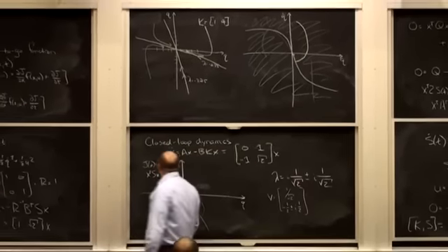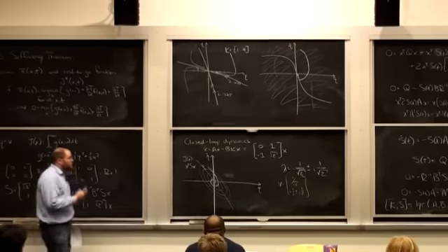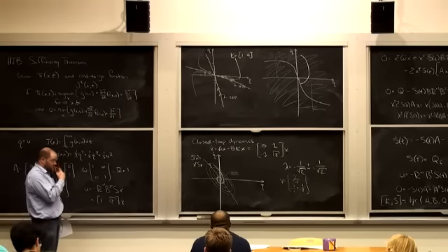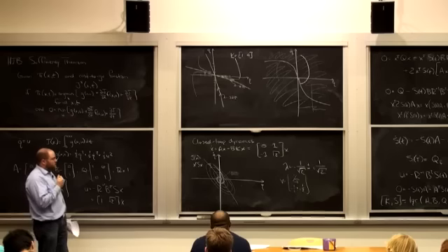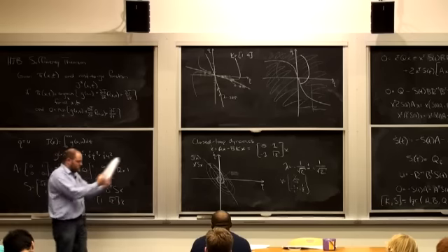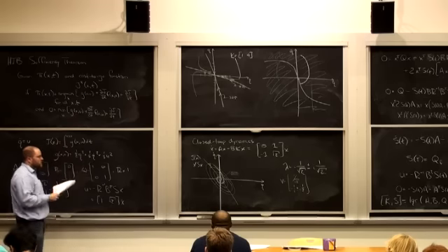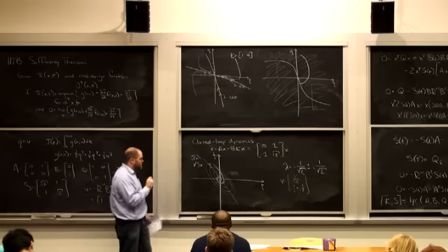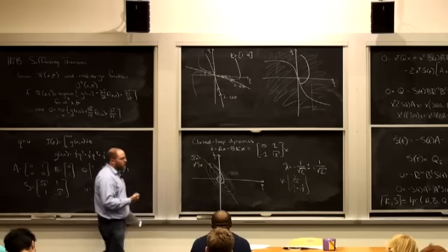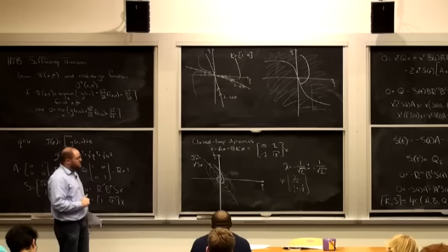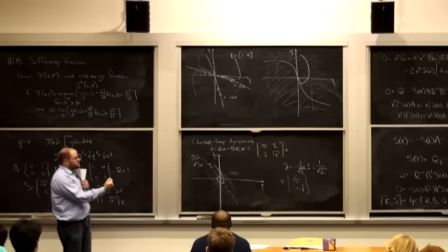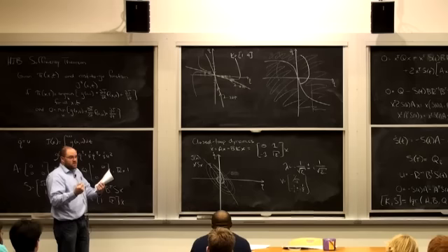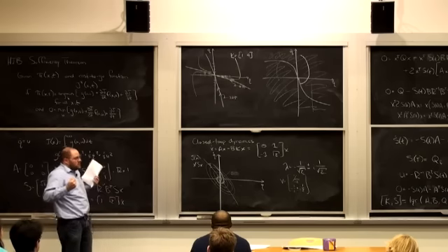Now, for the double integrator, the brick on ice, we could have just chosen our K's by hand and pushed them higher or smaller. We could do root locus. We could figure out a pretty reasonable set of feedback gains to make it stabilize to the goal. LQR gives us a different set of knobs that we could tune. Now we could more explicitly say what our concern is for getting to the goal by the Q matrix versus what our concern is about using a lot of cost in the R matrix.